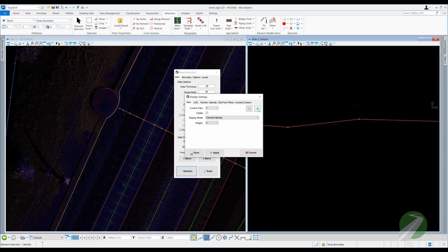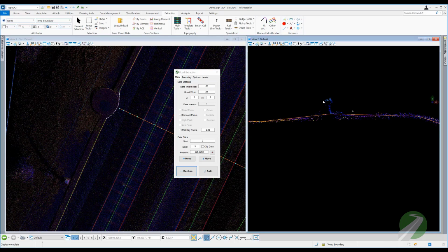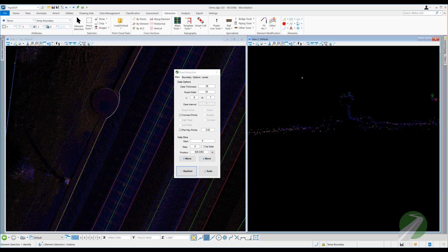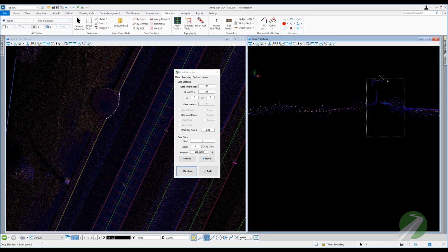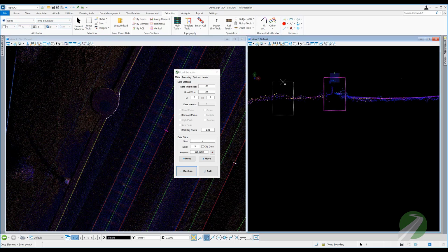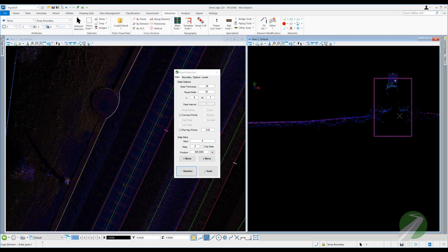You may notice that the rails themselves trigger breaks in the terrain when you don't want them to. We can solve this by classifying the data around the rail by creating a shape that fits the rail data inside of it, and then using the existing rail line to classify the data inside the shape along the rail element path.